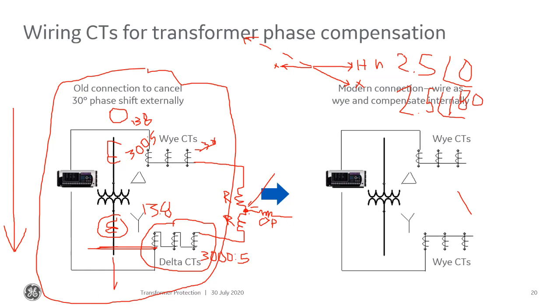It's a little bit complicated also because there was a filter circuit sitting out here, right? And that filter circuit was tuned to the second harmonic, and that filter circuit also provided restraint torque for the transformer inrush when you first energize the transformer.